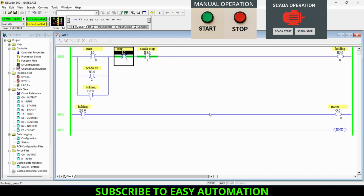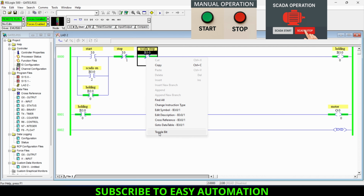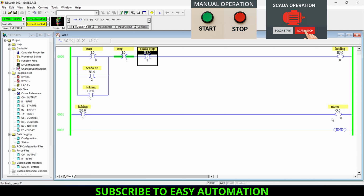But if I want to turn on our motor from the push button and turn off from the SCADA, let's turn on this motor by using the push button, and to turn off this motor I will use this memory bit which is being manipulated from SCADA. So whenever the operator toggles the bit from the SCADA screen, the bit will get toggled and our motor will go off, and whenever he untoggles the bit from the SCADA, the bit will get its initial condition. Like here in this case it will become NC again.